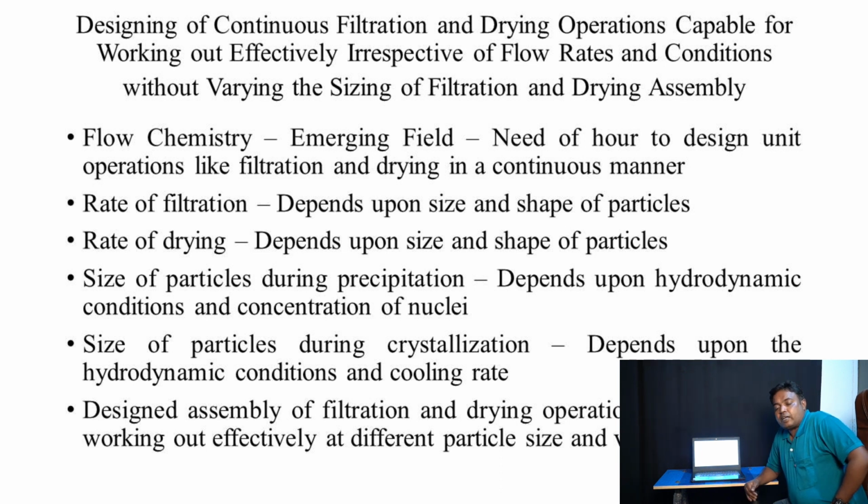The other aspect is that as the particle size decreases, the surface area per unit mass increases. Therefore, the total quantity of moisture adsorbed on the surface of the solid particles increases, and therefore the drying rate increases.